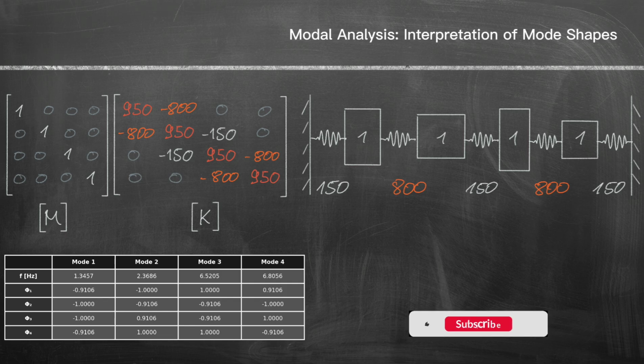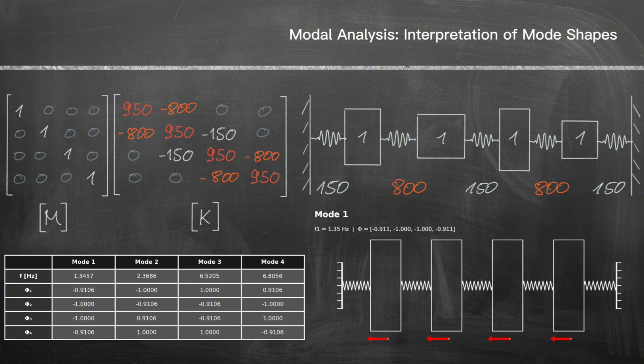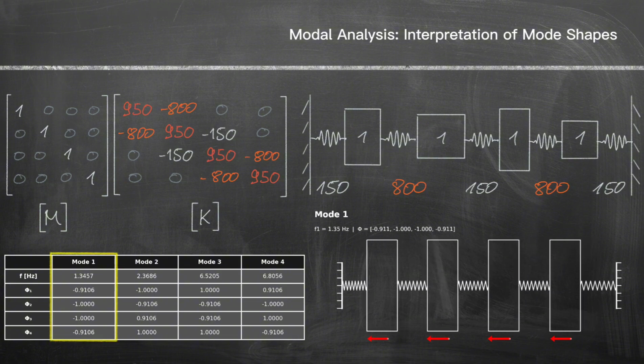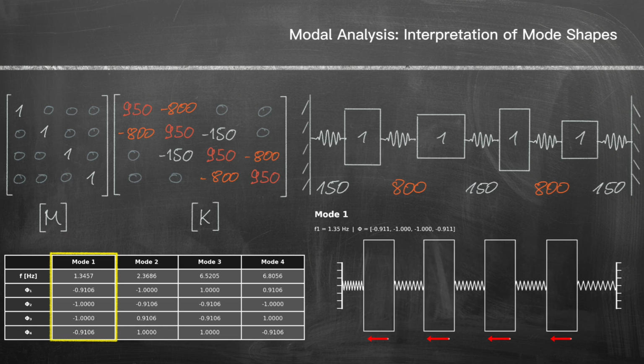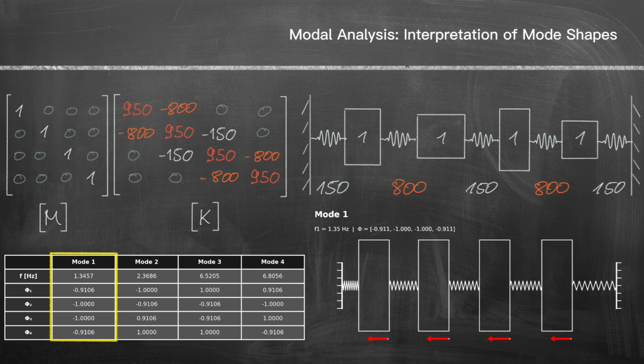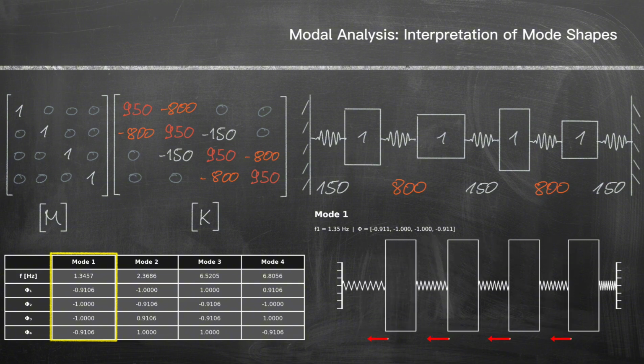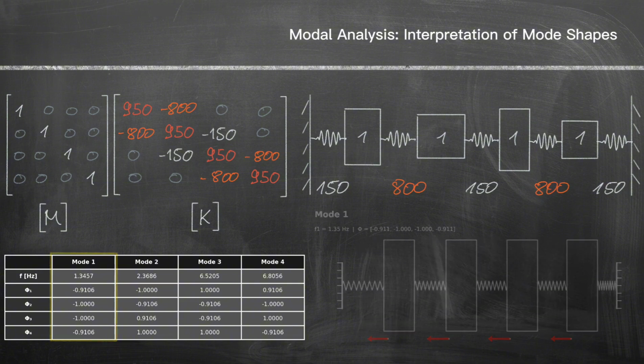With a strongly non-uniform stiffness distribution, we now observe a clear separation between global and local modes. In the stiffness matrix K, alternating large and small entries introduce preferred deformation paths. In global modes, several degrees of freedom move with comparable amplitudes. This occurs when the stiffness couplings distribute deformation across the structure, resulting in similar eigenvector components.